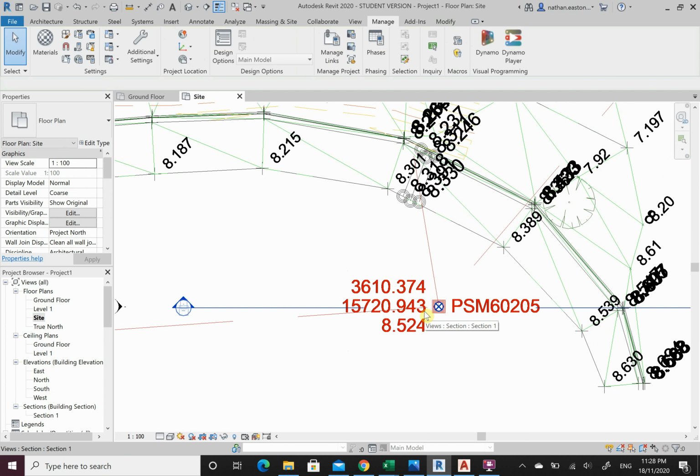Alright, so now that is in there, what I'm going to do with this part of the recording is we're going to go through setting up the land, and then I'm going to come through putting in the site and fill, the cut and fill. So it's going to be split into 2 different recordings, or even 3 recordings. So the next thing we're going to do, now that I've pinned and set my levels appropriately, we're going to go create the surface.